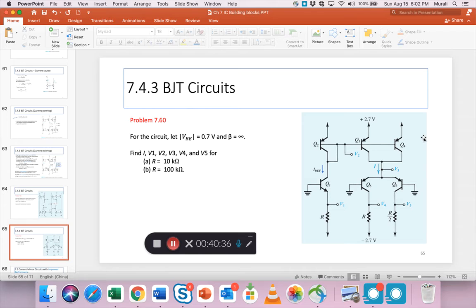Not very clear again where we should be looking for the current mirror, but this I reference I put here, and I recognize that Q1, Q2, just because it's Q1, Q2 and there is an R, you can think this is the current source that gives us our first current, which then becomes translated everywhere.